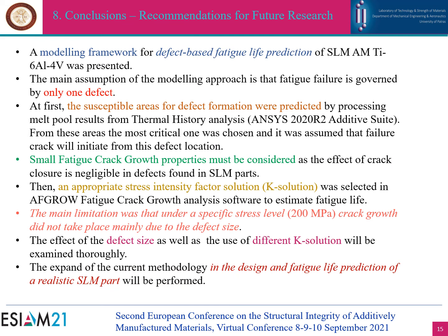To sum up, the main conclusions of the presentation are: a modeling framework for defect-based fatigue life prediction of SLM Ti64 was presented. The main assumption of the modeling approach is that fatigue failure is governed by only one defect. At first, the susceptible areas for defect formation were predicted by processing multiple results from thermal history analysis performed in ANSYS Additive Suite, and from these areas, the most critical one was chosen, and it was assumed that failure crack will initiate from this defect location.